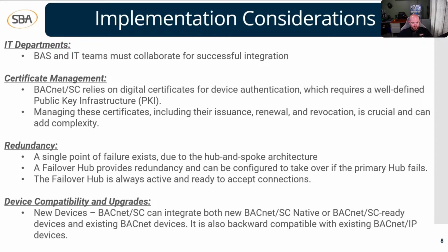And then the fourth thing for implementation considerations is device compatibility and upgrades. BACnet Secure Connect can integrate with both new BACnet Secure Connect native devices or BACnet Secure Connect ready devices. It's also backwards compatible with existing BACnet over IP devices. So these are things you have to consider when you're talking about upgrading these systems.